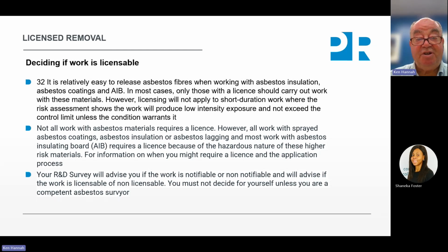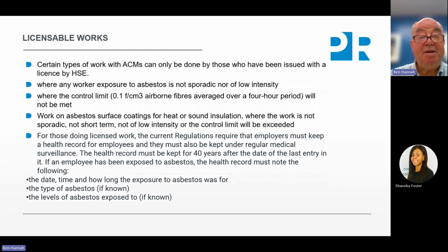For information on when you might require a license and the application process, look at your survey. Your survey will advise you if it's notifiable or non-notifiable, and if the work is licensable or not licensable. For licensable work, certain types of work with ACMs can only be done by those who have been issued with a license by the HSE.